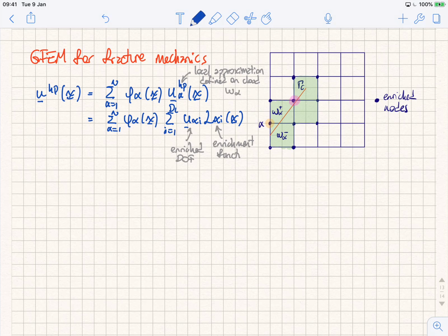That means basically that I'm extending artificially the crack till the end of the element, right? So in a way, if I add an enrichment function and the Galerkin framework is assigning a non-zero enriched degree of freedom that is associated to that enrichment function, this basically translates into that strong discontinuity splitting completely the element. So in this case, to solve this problem properly, you have three types of enrichments that you need to add.